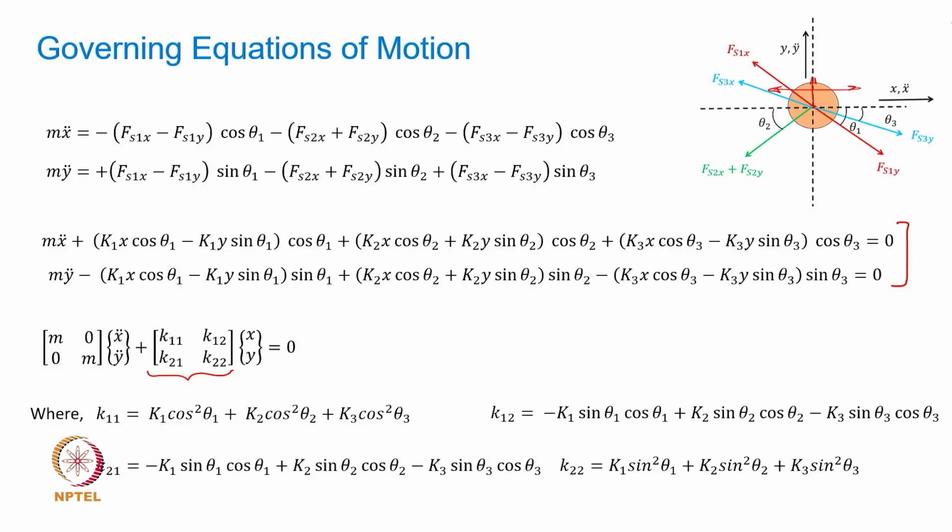because of the peculiar configuration of this particular system. Okay, if we arrange these springs in such a way that the restoring forces are completely balanced, for example, if I place them symmetrically, the spring constants are identical and this angle is 0 degrees, and then if I try to move this mass, there will be no restoring force in the y direction. So then I can have x motion happening completely independently. But in general, this is how the stiffness matrix will look, and you can then solve this governing equation of motion to get the eigenvalues and eigenvectors as we discussed.